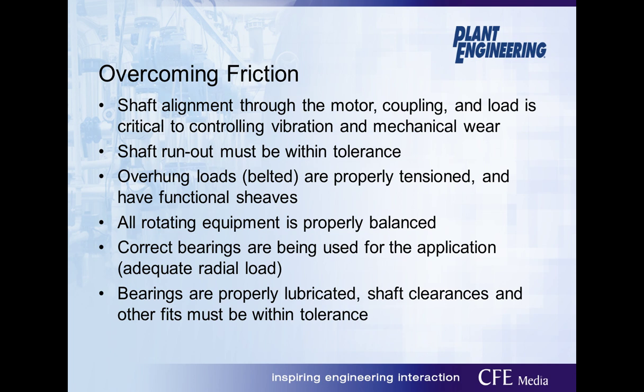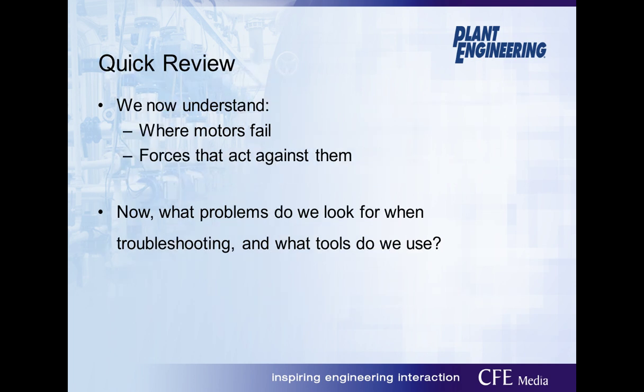And just to reiterate, kind of where we started, bearings are the number one cause of motor failure, so it is very important to follow preventative maintenance routines with your bearings, such as periodic lubrication and vibration analysis. Even when greasing the bearings, verify that proper lubricant is being used and the proper amount of lubricant is being added. Bearings should be maintained based on run hours. Product literature from the bearing manufacturer specific to your product can give details on lubrication type, interval, and amount.